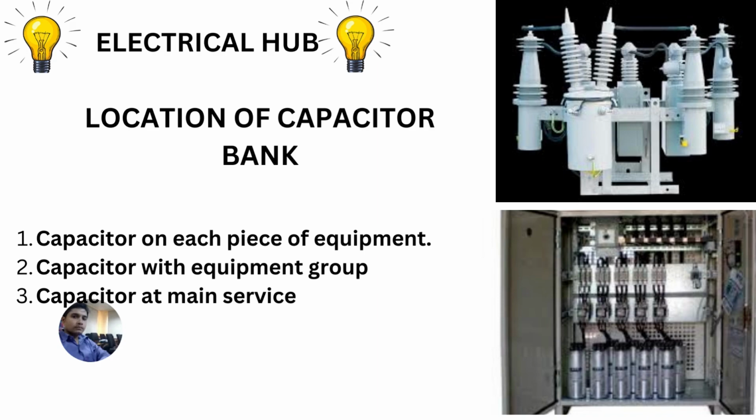Now, third, the capacitor at the main service. Low material and installation cost. But the disadvantages are switching will be required, and it does not improve the load capabilities of the distribution system.